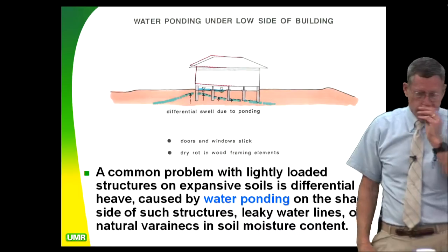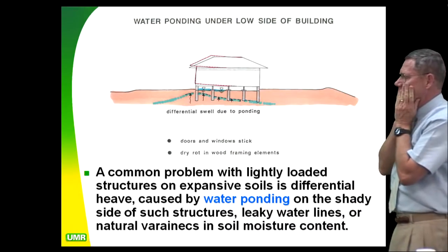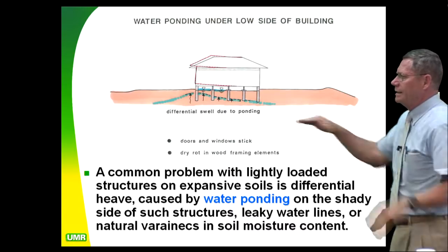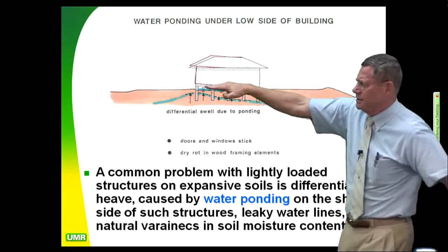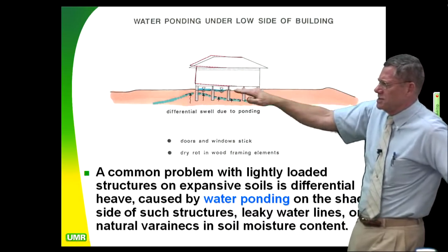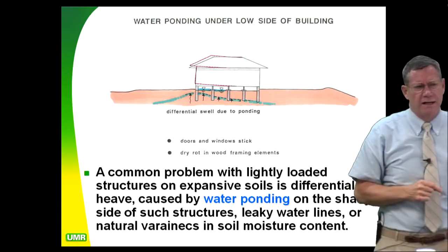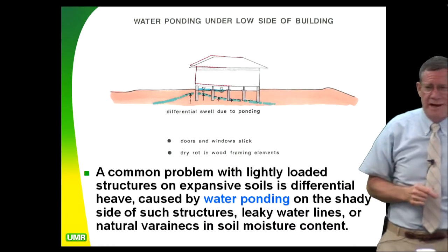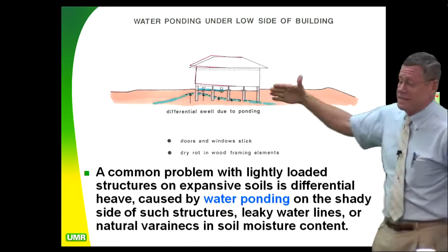Now, more common than not, when you start getting situations like this, if you do a water level survey on the house, you'll start finding the house has a low spot. And the people call you and say, my house is settling. 9 times out of 10, their house isn't settling. It's the other side of the house that is what? Heaving. Yeah, so you go in, it's just a relative thing.